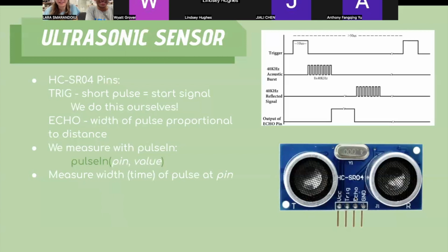And so if the sensor does not receive the ultrasonic wave within a certain time, it times out and just returns some maximum value. This is how we measure the basics of how far something is. We'll be using this sensor for the main axis of the car, so forward basically, for the hand following, or to the side for the wall following.